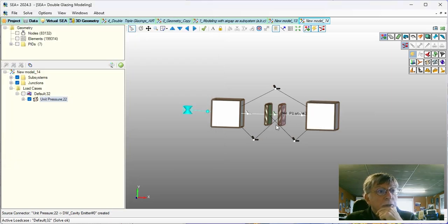So in fact, most of the energy is coming from plate 1. What it means is there is looping. In this model, you have non-resonant energy going in the cavity, and at high frequency, this non-resonant energy in the cavity is radiating back into the receiver plate. That's a fairly complicated path.